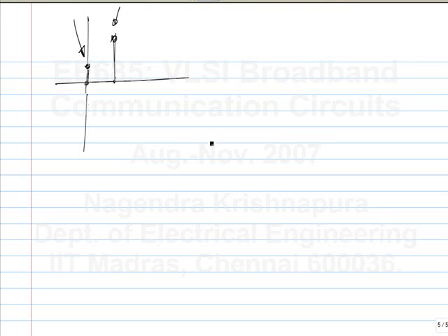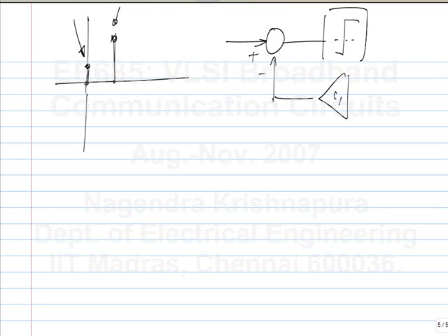Why do you say you need to delay the input? You get some input, that's it. In case of DFE, for this particular system, there is no non-causality, right? There is no non-causality at all. If you have precursor ISI, it just says that the second one is larger than the first one, or some later one, right? So the only thing that means is this, let's normalize everything to, let's say this is 1 and this is half. Okay.